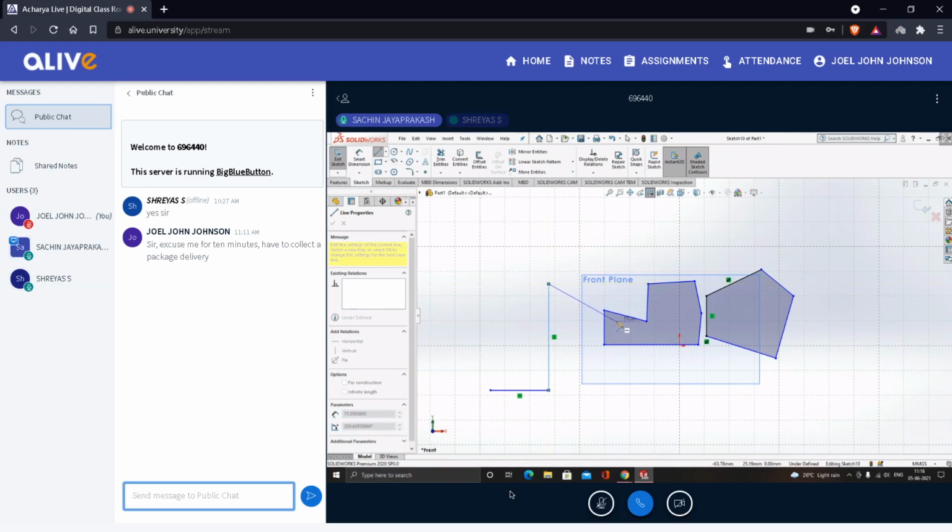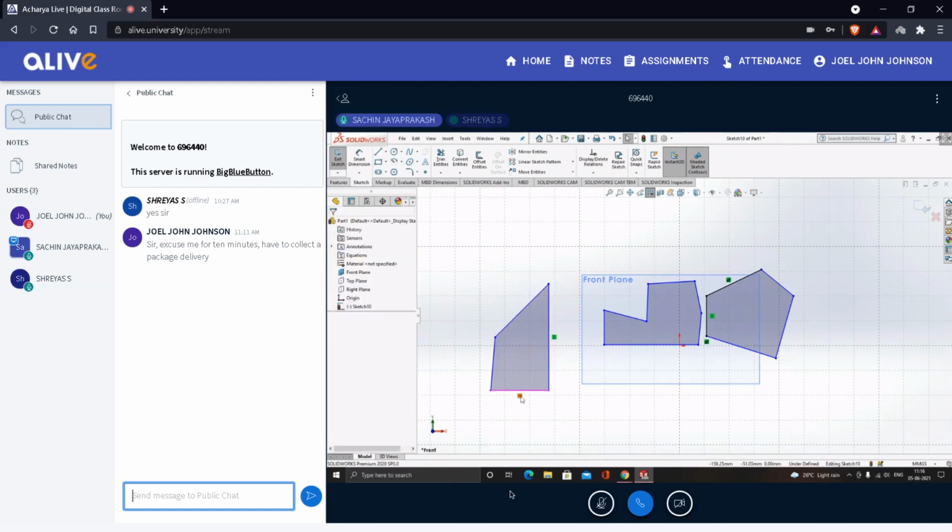Okay, similarly a constraint comes here, look, not here, I'll do this side. Okay, so there is a minus 35 degree constraint, so 45 degree. If I click this, again that constraint is applied. Similarly, when I click here, a point constraint comes. Now the E line is fixed. Basically this point is completely fixed.